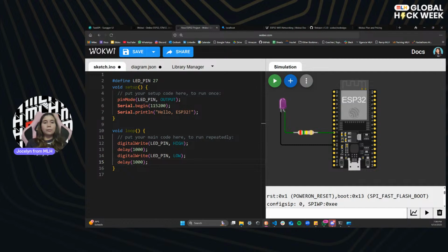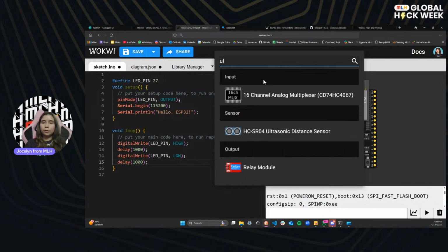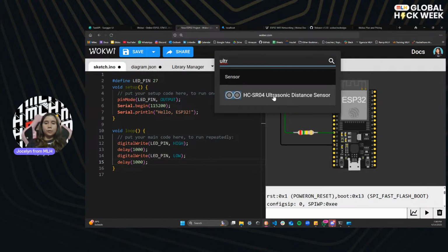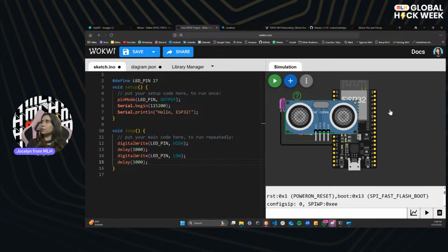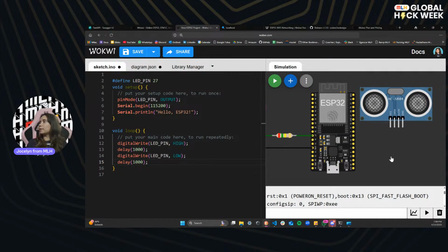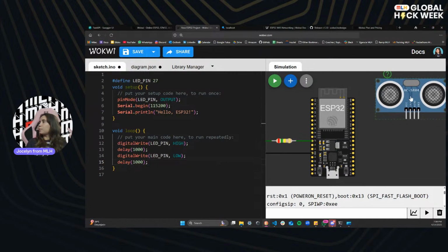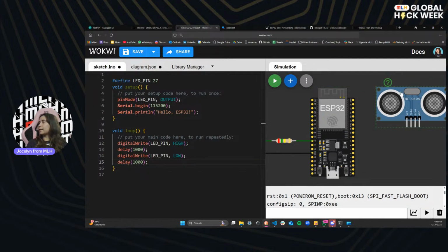So we're going to see if we can connect this into our circuit. The first thing we need to do is add our ultrasonic component over here. So it's this one, ultrasonic distance sensor. Let's grab one and put it on the side over here. By now, I don't need another breadboard because I have another ground over here, and I also have another 5V over here, and I have more digital pins on this side.